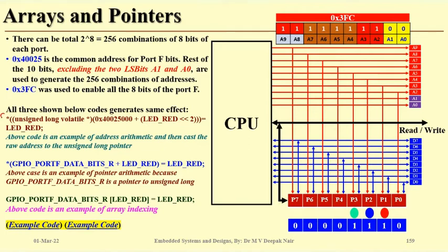Otherwise this particular statement is also very difficult to read, because always you have to go to this particular register, and for that you write the whole lengthy code and then introduce something. You don't have to do that. What we can do is we can use macros. We can replace this whole line from here to here using a macro like star GPIO F data bit register, or whatever register you want to call that. So this is another approach.